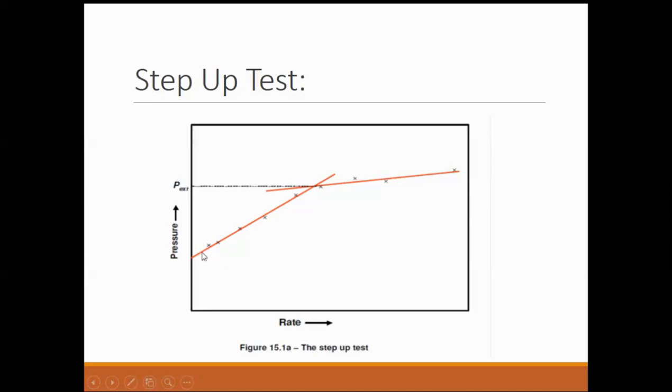Sir, do we use the same wellhead for production and fracking? No, they are different wellheads, because for fracking you will generally have expected pressures higher than your production pressures. Generally, while fracking the peak is between 5,000 psi and 10,000 psi, while producing the same wells will have a pressure below 5,000 psi.